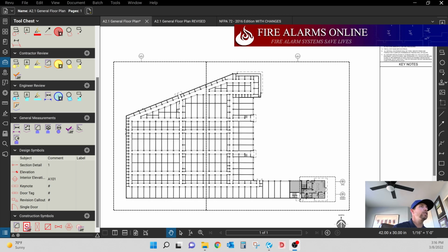Before we get started, just know that Bluebeam is basically a glorified PDF editor, much like Adobe or Foxit. It just has a lot more useful tools in terms of doing takeoffs and counts and scaling documents. So if you have Bluebeam and have opened it and not really played with it, it's going to look somewhat like this in terms of the profile setup. You've got some tools over here on the left, a toolbar on the right, and a minimalistic approach up here at the top.